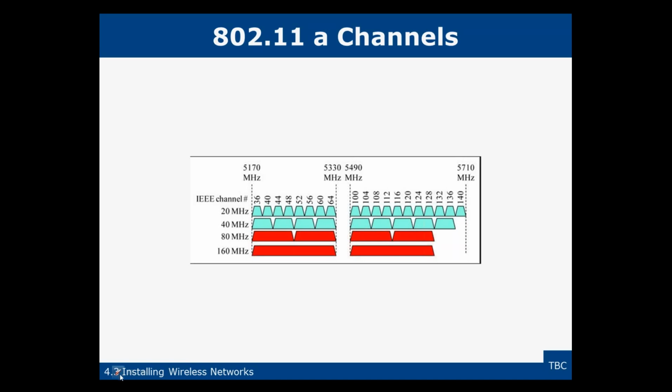What this represents down here is what's called channel bonding, so that instead of doing single channels, we can put channels together, and the more channels that we can put together, the higher the data rate that we can get out of here, because this is a true bandwidth, how much frequency that we have to use. We have this much space to put data on.